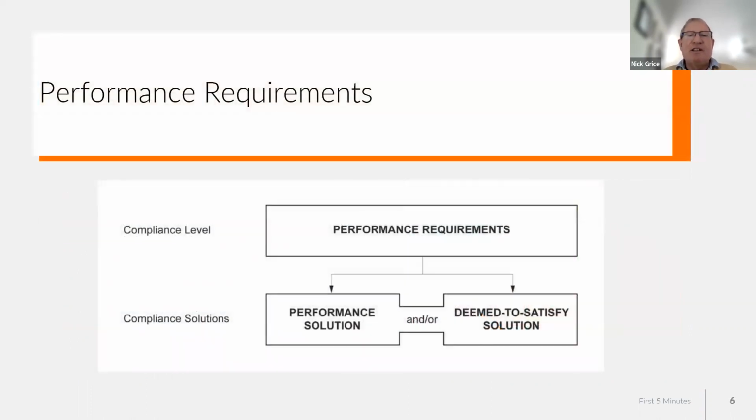So there's a lot that goes into these fire engineering reports. As we said, we've got the compliance level, which is the performance requirements of the building, and you can achieve that with what they call deemed to satisfy. That's a prescriptive solution within the National Construction Code. So you just build a building with that, and you don't need a performance solution. But you might need a performance solution. Let's say a travel distance, for example, has to be 25 meters for deemed to satisfy, and it's been taken to 35 meters. Then they've got to put a performance solution in if they don't put another exit in. It might be something like putting in a fire door, sprinkler protection, extra smoke detectors, and then they will formulate this brief, which will then formulate a report, send it to the fire service, all the rest of it, and then accept it. You with me?